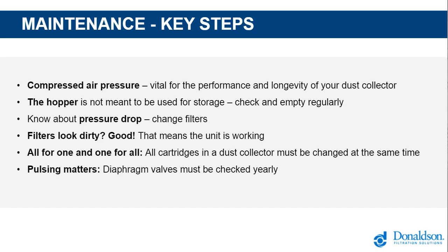As we all know, with reverse jet filters, there is a time between pulses. It's making sure that we have the correct compressed air pressure, the right quality, and the right volume back up to the right level for the next pulse.